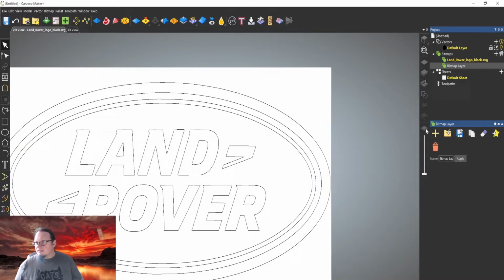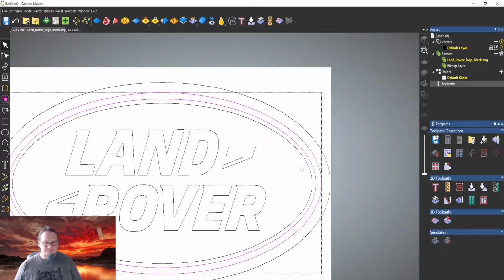So let's get started. This one works very different when it comes to programming your toolpaths. It doesn't matter which way you sort of start. So if we select this line and this line, holding down so that I can select multiple lines. If I click the first line and then click the second line, it will just switch. But if I hold down Shift, I can select multiple lines. So we're going to come over there and we're going to click on Toolpaths.